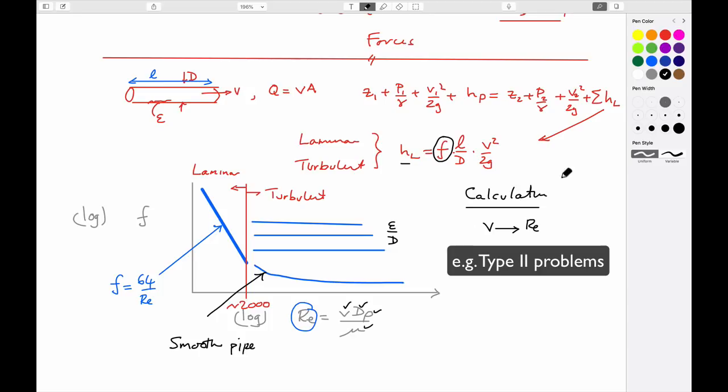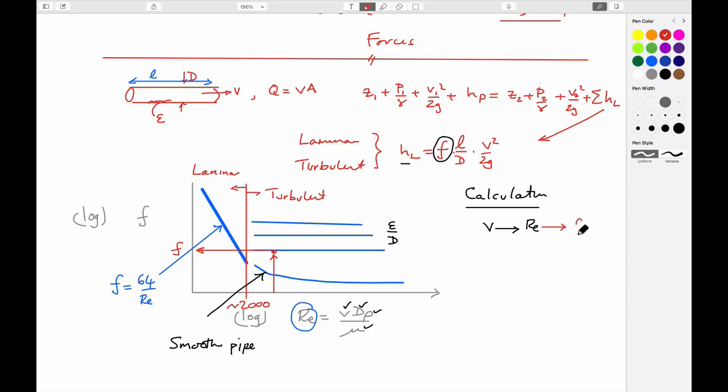If you know the Reynolds number, then you can certainly calculate, for a given friction factor, say, or a given roughness, a magnitude of the appropriate friction factor. And if, for instance, it was in this region here, it'd be straightforward, because as you change Reynolds numbers, you don't change friction factors very much at all in the turbulent regime.